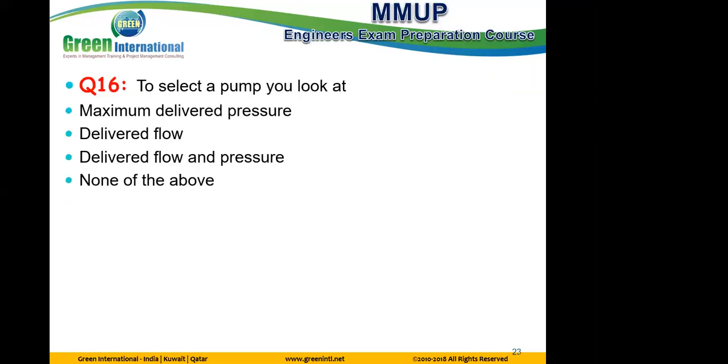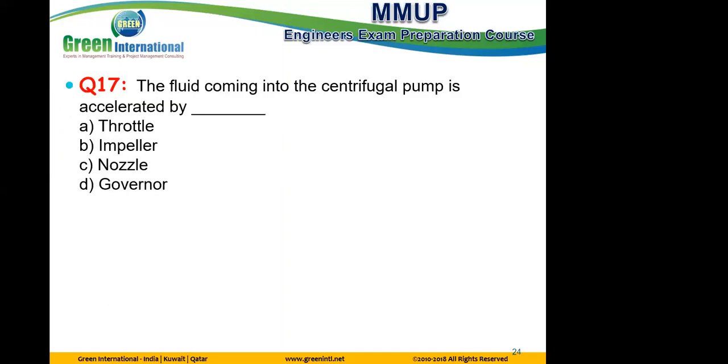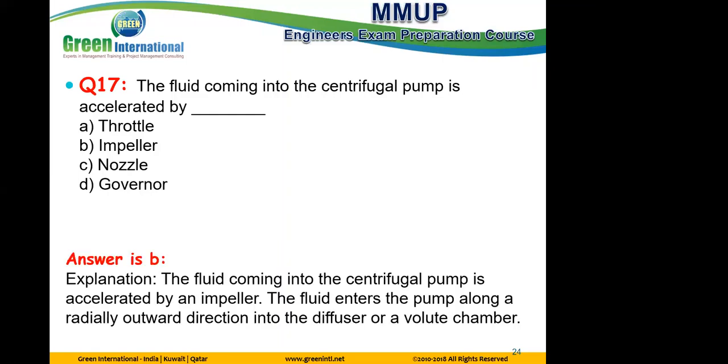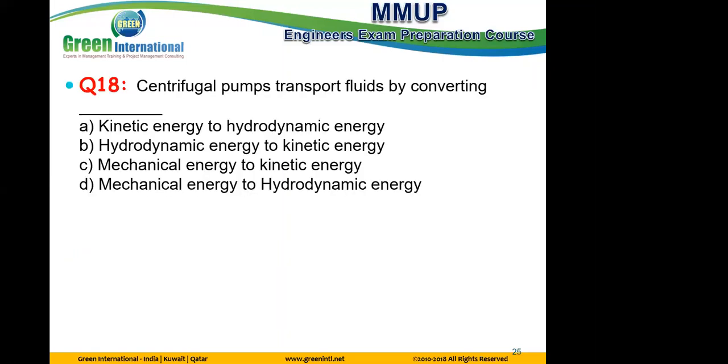To select a pump, you look at delivered flow and pressure. Yes. Fluid coming into the centrifugal pump is accelerated by the impeller. Centrifugal pumps transport fluid by converting mechanical to kinetic energy, mechanical to hydrodynamic energy.